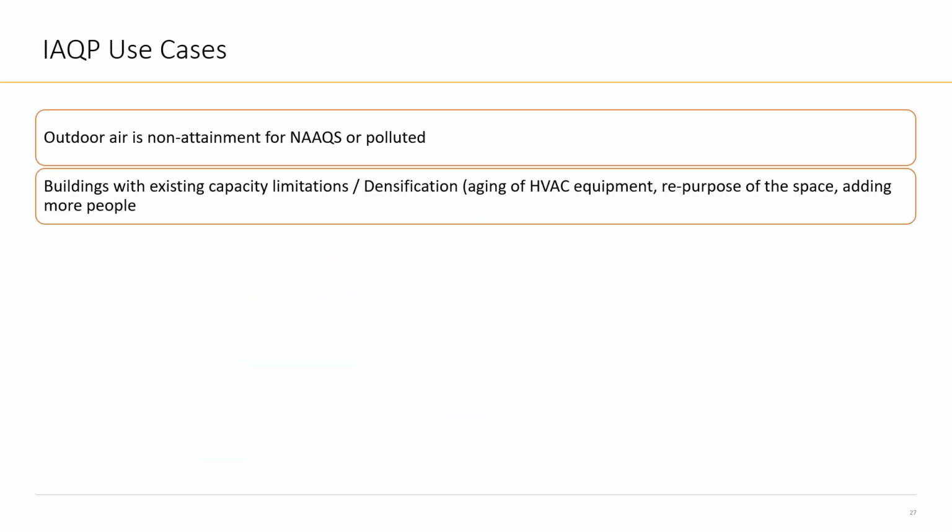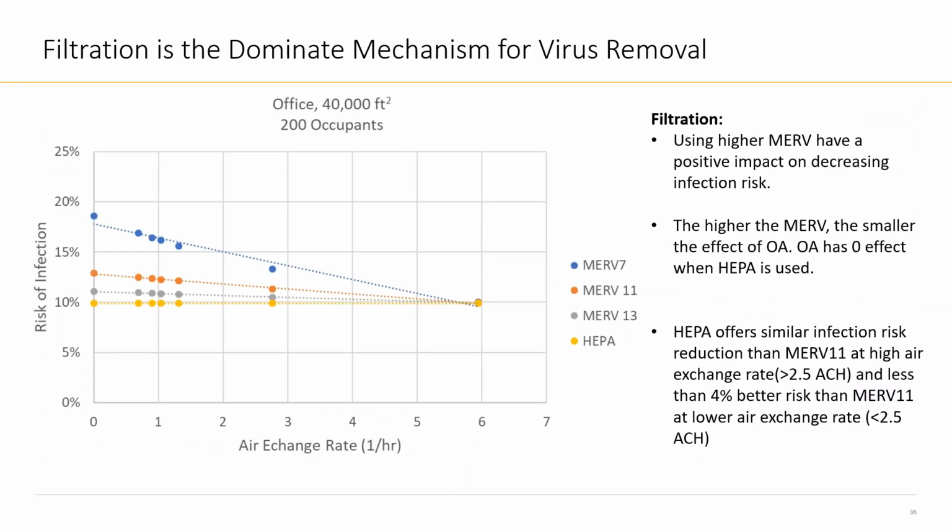Now, I don't know if you remember the measles in New York schools. Measles in New York schools, it was this guy, Riley, based on the Wells-Riley model, that says basically you have an equation, and this equation takes into account multiple things. One of them is called quanta. Quanta means how many of this disease you have, the number per hour, that can infect you. There is the size of the virus that we're talking about, and then you can include different filtration and ventilation.